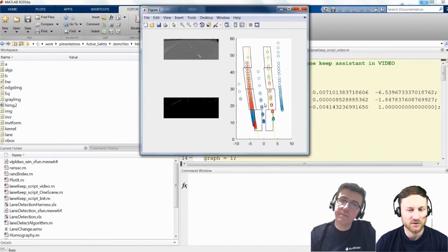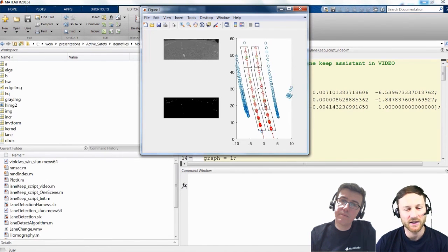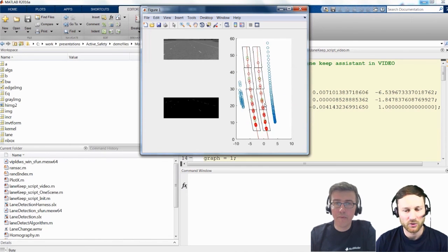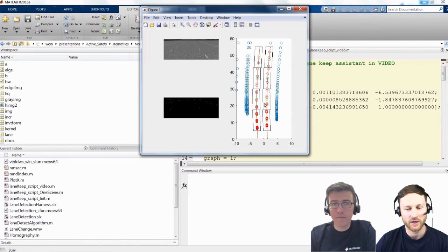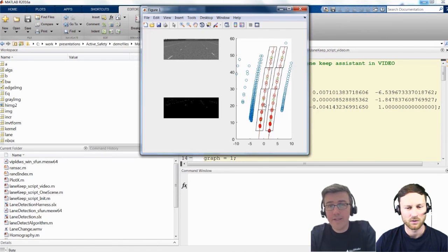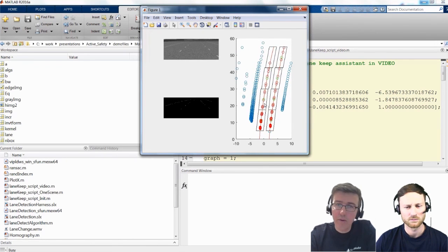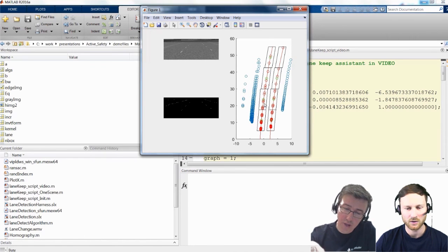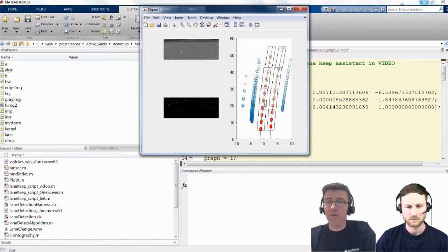Well, I believe that this is running in MATLAB. This is all working nicely, but at the end it has to run on a car, probably on an ECU or on a microcontroller. How is the workflow to get it running on a proper car? So the workflow. First of all, you can design your algorithm without thinking about the final implementation. So you define the mathematical concept and the mathematical algorithm, and then you can use the MATLAB code or the Simulink model that you have developed and generate C code, which is also embeddable on your microcontroller and DSPs to